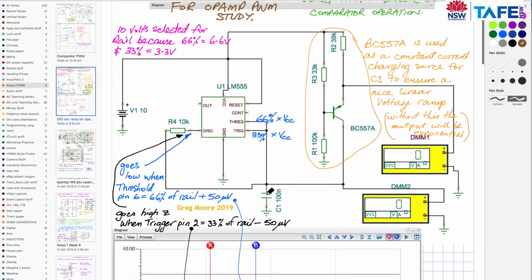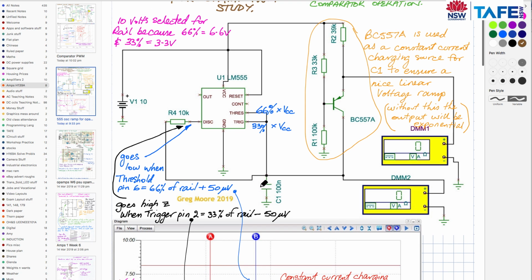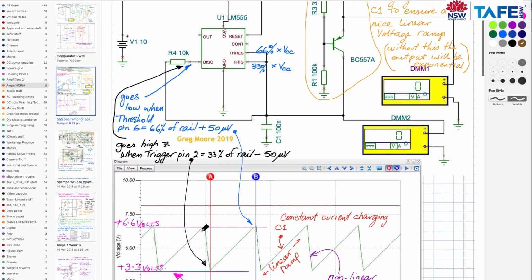And normally when we charge a capacitor, it starts off charging, drawing a lot of current, and then as the voltage across the plates reaches the supply voltage, the current that the capacitor draws for the charge drops away to almost zero, and then finally is zero. But in this case, we don't want an exponential curve, which would normally happen. I want a linear curve, so I've had to use a constant current feeding the capacitor, which does in fact result in a beautiful linear curve.